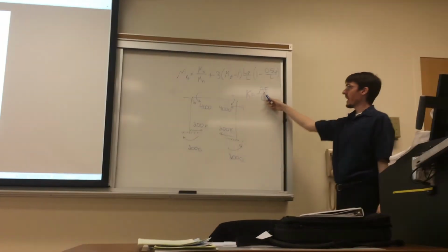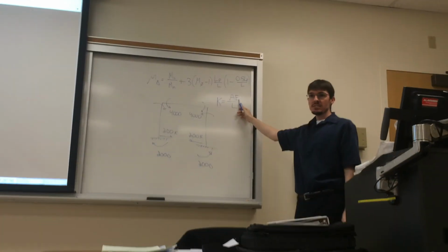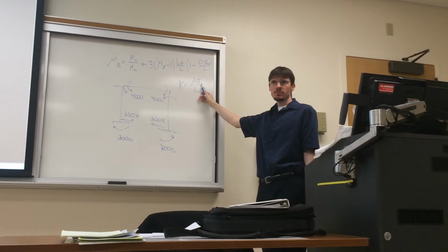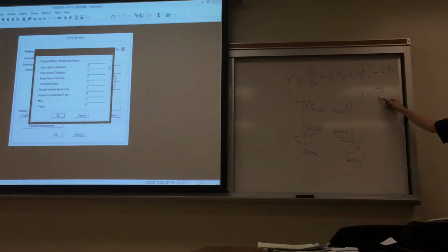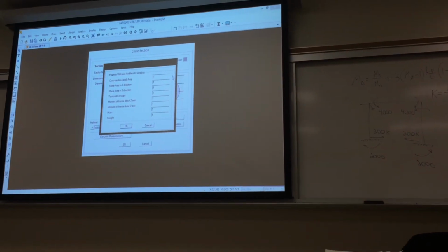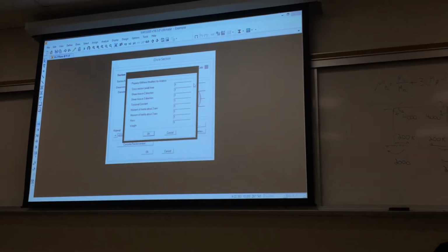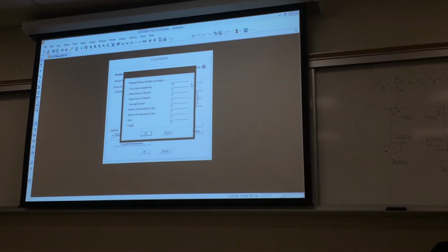You can increase either A or E, but E in this case is being used as an actual value for, let's say, our deformations of this frame. So we don't want to mess with E. L is also kind of a fixed value of our frame. That's an actual geometry. But A, we're not really using for anything. It's kind of a throwaway value in this case because that's only really used for axial deformations.